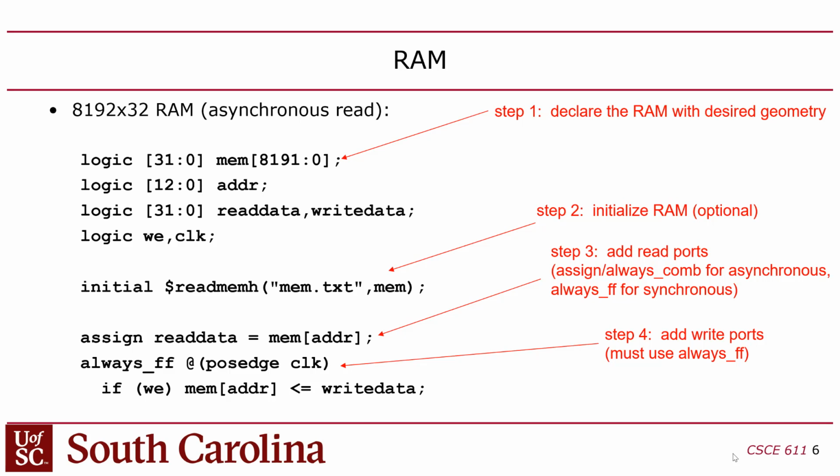You guys with me? Now, in parallel to that, though, in fetch, you're also going to be incrementing your program counter, right? As a counter, you're going to be ticking up the program counter. So you're going to be doing those 2 things at the same time, concurrently in parallel inside the fetch stage.